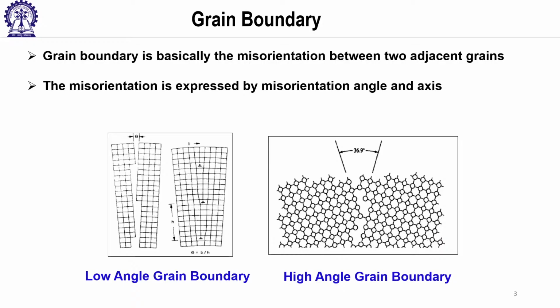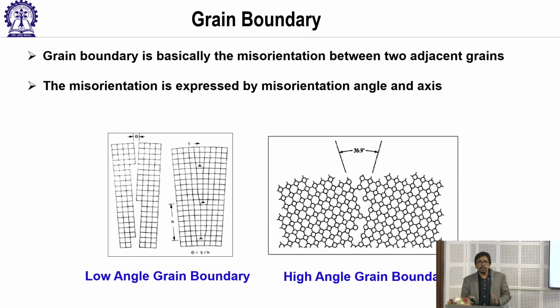Those things we will not go into detail because then we have to consider the grain boundary plane and all those things. Today's discussion will mainly focus on the misorientation, because the coincident site lattice or CSL boundaries concept is based on the misorientation alone, it does not consider the grain boundary plane. So this will of course be a simplistic assumption, and some of you probably know that grain boundaries have 5 degrees of freedom, 3 come from the misorientation and 2 come from the plane.